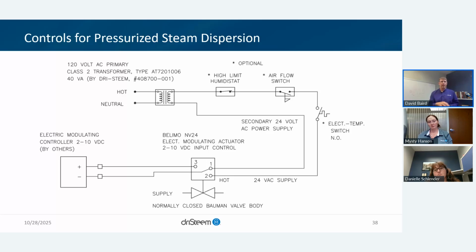Then you've got the controller sending in what is the amount of demand required. Think of this as that humidistat because, again, there's no VaporLogic. It's demand by others. So this is a way to accomplish that for a pressurized steam, a steam injection type unit, or an Ultrasorb connected up to a boiler, as an example.